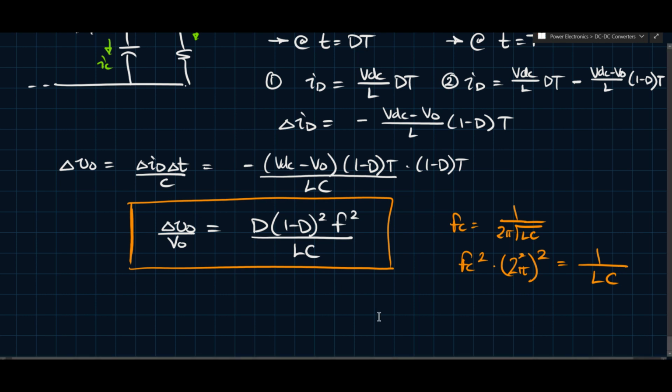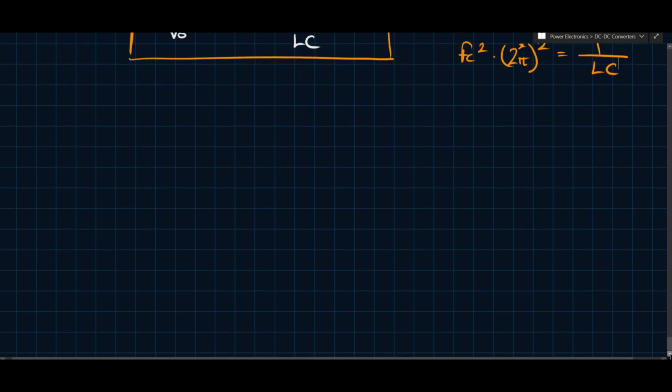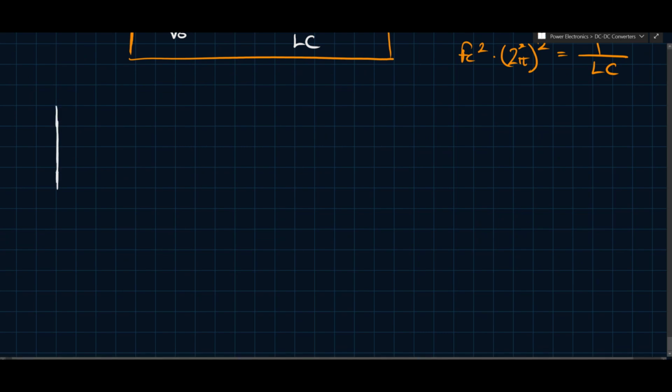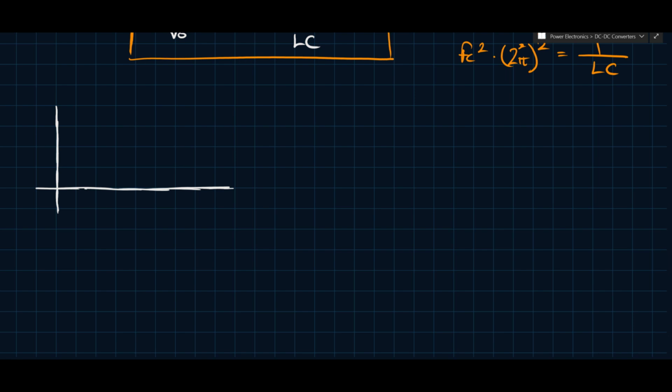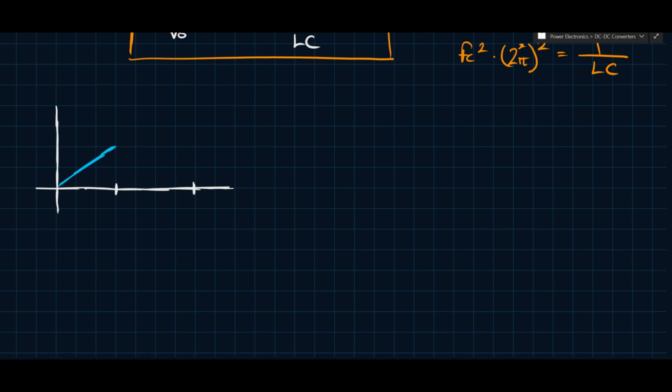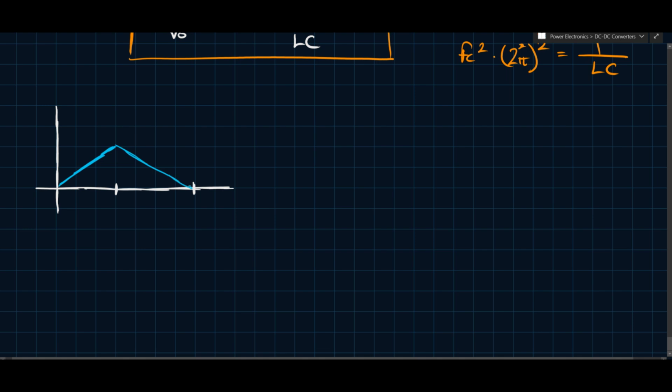And so the last thing we should talk about here is the concept of continuous and discontinuous conduction mode. We saw already for the buck converter, if you haven't seen that already, I've linked that video as well. In the case of the buck converter, we saw that discontinuous conduction mode essentially happens when your current hits 0. So let's imagine that this is going to be our period, this is dt. So your minimum current ends up being 0. So your IL min is now 0. So if this is IL max and this is IL min